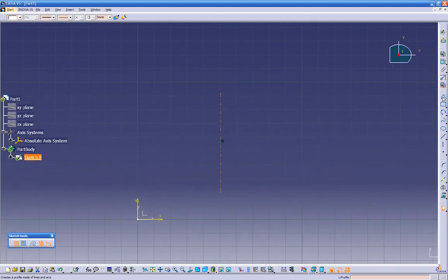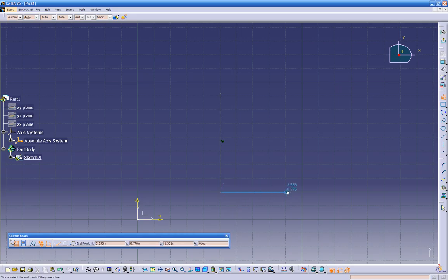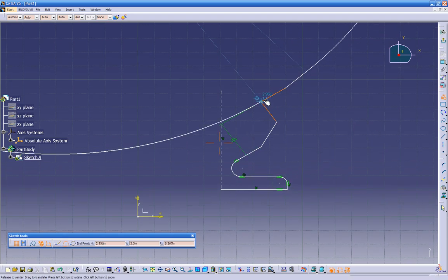And we can go again to the profile and try to build the sketch. As I mentioned before, when you use the profile, if you quick tap, it just creates lines. But if you click and drag, it creates an arc. Okay?